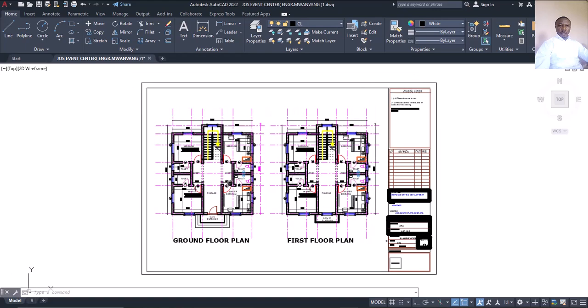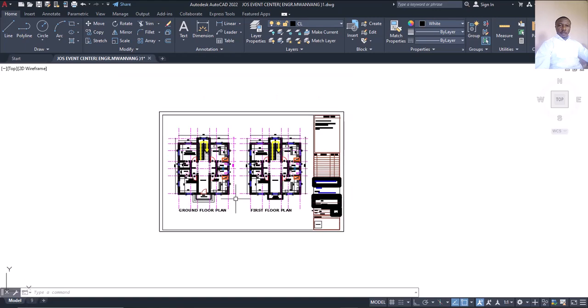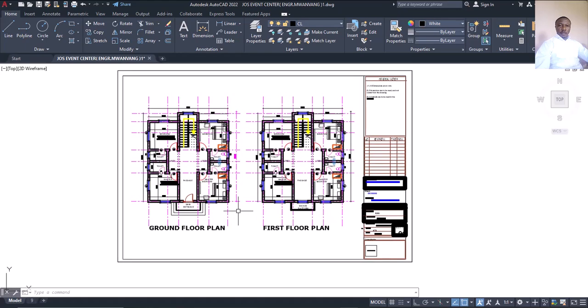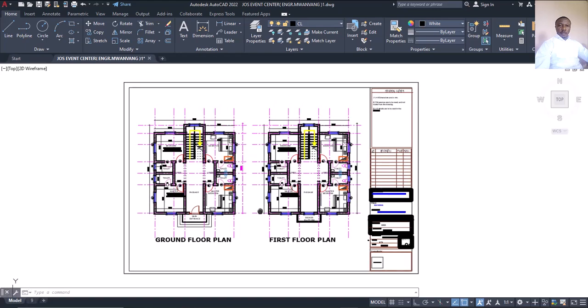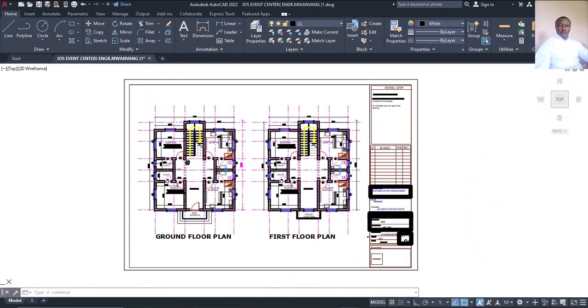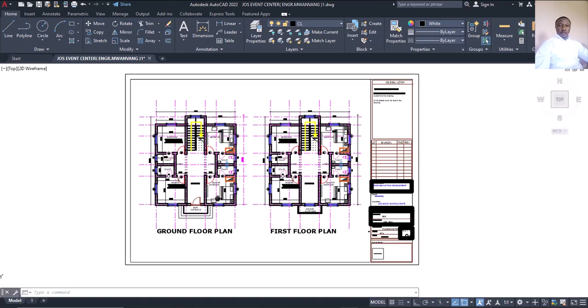Okay, so let's start. The moment you receive a drawing from your architect, what are you expected to do? You cannot jump step 1 and start step 2. There's something you must do first, which we call GA, general arrangement, or structural framing. Structural framing means the structural elements and their positions, how you are going to position them. We have to do it here in AutoCAD before we proceed to using our software called Protastructure. Not to waste our time, let's proceed.